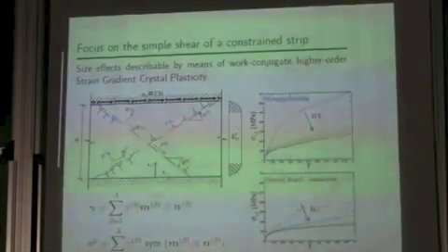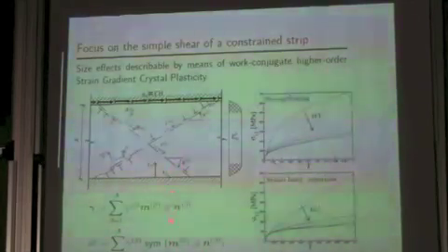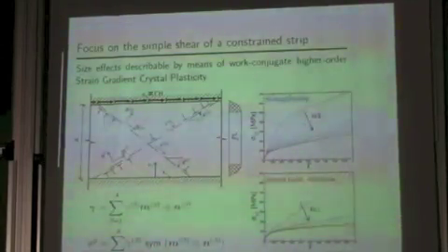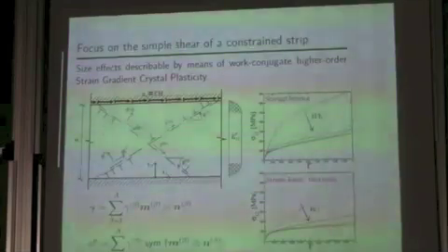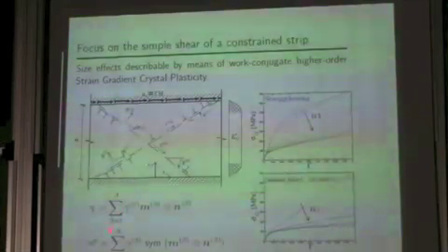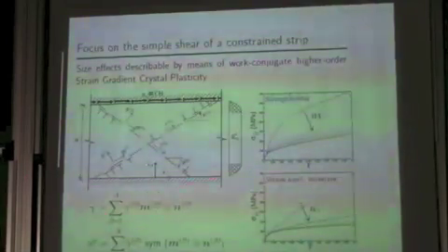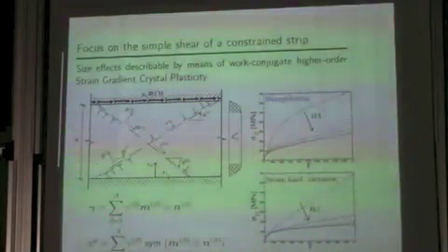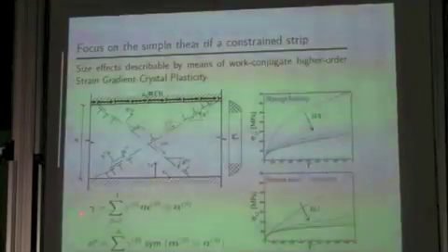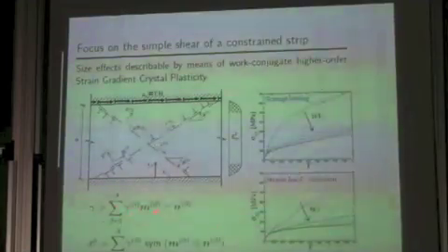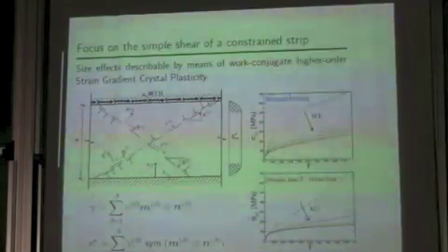And sorry, there is some cut here, but in strain gradient plasticity, two relevant measures, actually in any crystal plasticity, relevant measures are the plastic distortion. This is just to introduce my notation, it's trivial stuff. You construct the plastic distortion by summing over all the slip systems of this product.